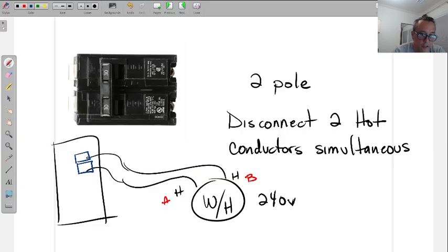Now, in a pinch, can I do this and just resolve it for the homeowner maybe and get them working because I didn't have one of these in hand? Okay. But the reason why I can't use two separate individual single pole breakers is because they shut off independently of each other. So if I shut one off, the other one doesn't shut off along with it. And they're not worried so much about shutting off, because if you shut off one, you're standing in front of the other one, you can shut it off too.